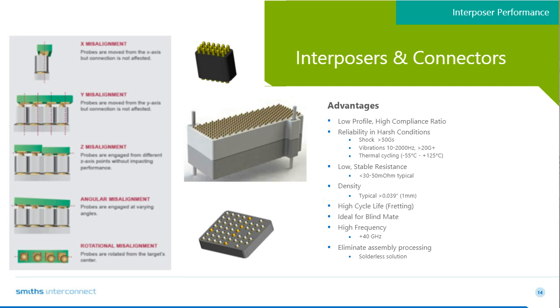Sorry about that. So now we're looking at some of the advantages of integrating a spring probe connector or an interposer into your system level designs. Going through some of the key points we are showing here, you'll see us mention the ability for low profile to high compliance ratio, also referred to as our travel. Typically, a 4-to-1 height to available travel is standard. The ability to survive and operate through harsh shock and drive environments.